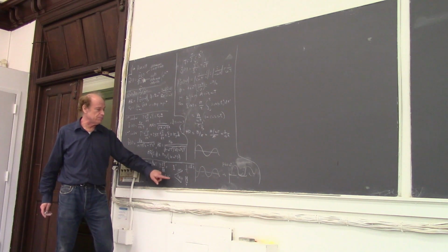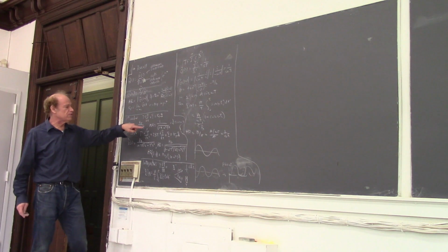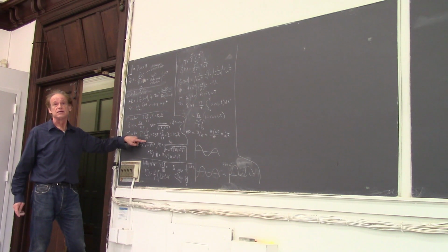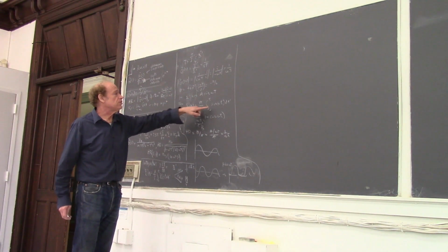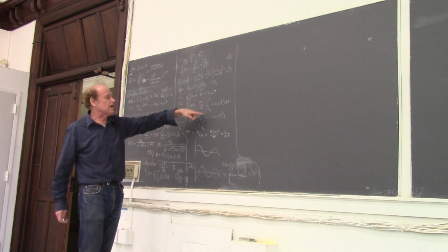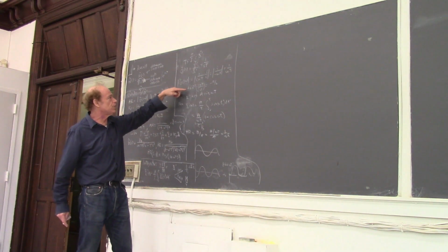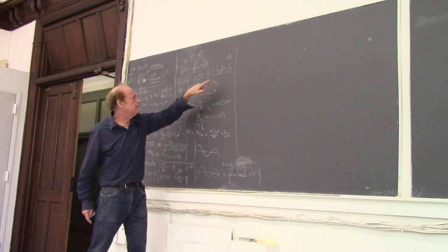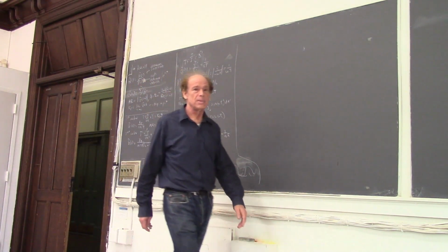When I have a pulse, it gives me a constant. Remember that the self-correcting system forgets a pulse eventually. And when we have a sinusoidal input, then we still have an oscillatory output, but the amplitude ratio and the phase lag are what we're able to determine here. Any questions on that?